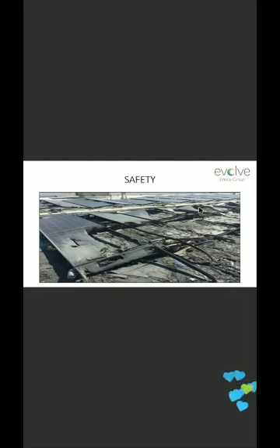The root cause of this problem was noticed: the system had a low thermal hotspot, and it caused the backsheet to crack and the cell bus bars to bust. In that case, the improper grounding and the leakage caused the system to catch fire. So this is the seventh incident that happened continuously to Walmart, so they are having bigger trouble in this.